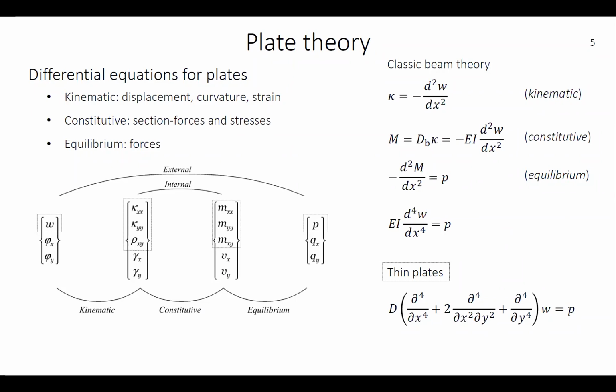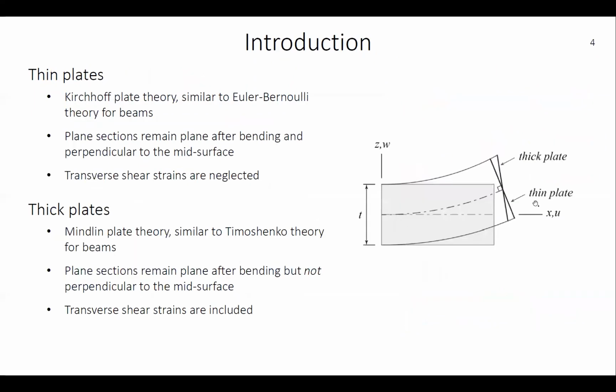So when it comes to the differential equations for plates, you separate those in kinematic, constitutive, and equilibrium equations, where the kinematic ones are the displacements and curvatures. The constitutive ones are section forces, and the equilibrium equations are related to external forces. So if you have an example of a classic beam theory, we only have the displacement w, as we saw from the previous picture here.